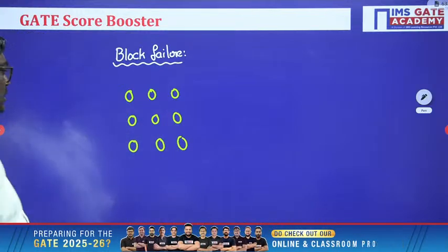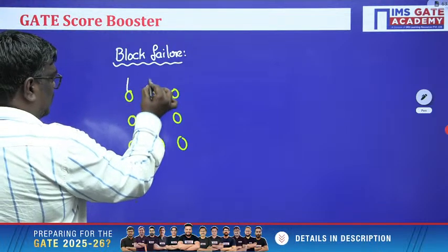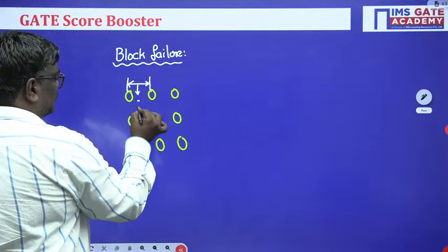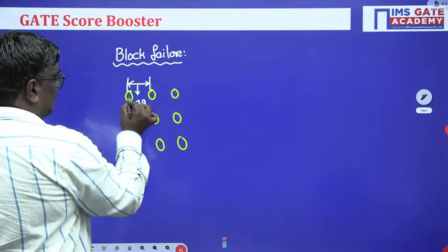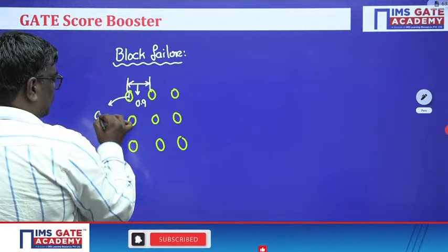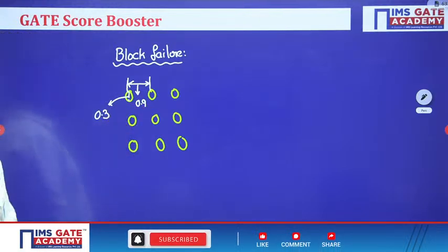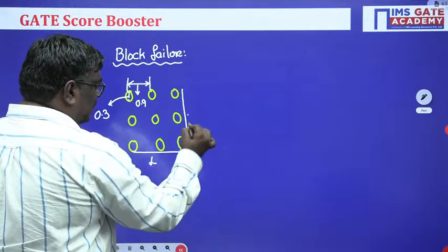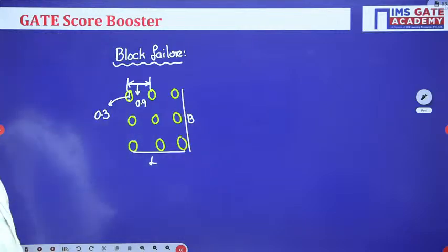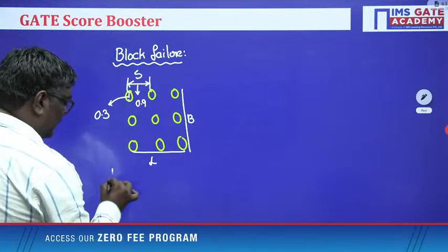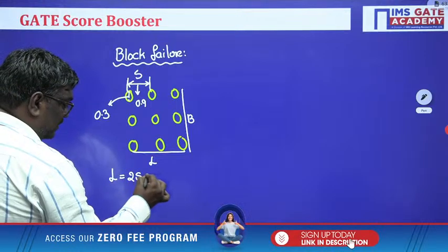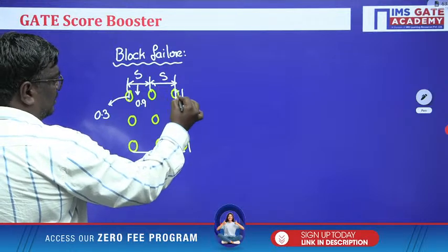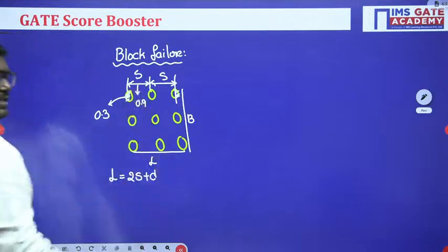Okay, here see, the spacing between the piles is how much, sir? 0.9, and the pile diameter is how much? 0.3. So it's a square group, right? Here L and this is B, both will be the same. If I take this as spacing S, L will be equal to 2S plus D, because S, here half dia, here also half dia, so 2S plus D.